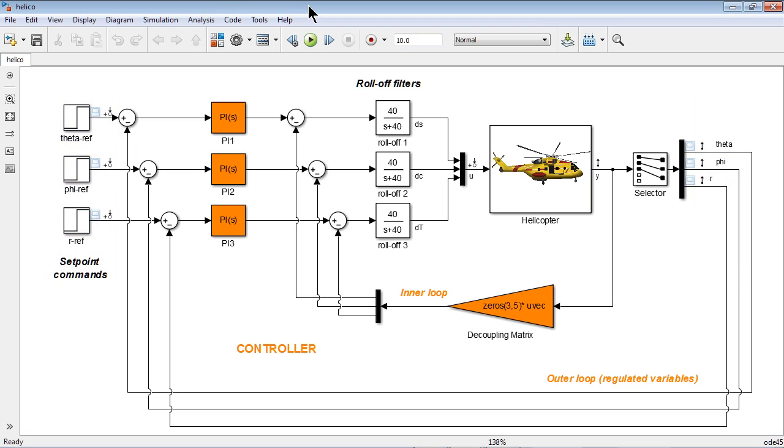The second and third requirements are to provide strong multivariable gain and phase margins at plant input and plant output correspondingly. And the fourth and final requirement is to limit how fast closed-loop system dynamics is, not to excite flexible modes of the helicopter. The system is initialized with default gain values.